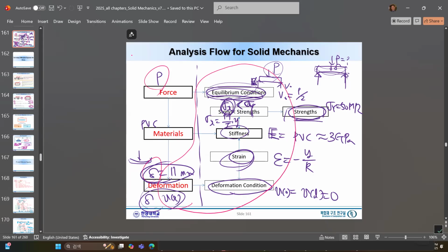And then internally, we get all the stresses and things like that. See, moment here, moment is what? EIV double prime. So if we know the Vx as a function of x, we can immediately get the moment, and we get the sigma, and then we get the maximum allowable P. This is a very important point.